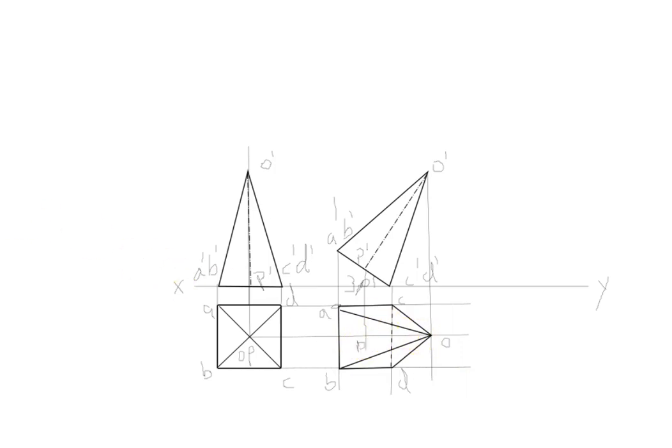Fine. So in fact we can also draw the axis. For example, let us do that. Let's draw a line from this to this and make that a hidden or dashed line. Now in fact that has to be not a dashed line, it has to be a center line. I'm sorry, it has to be a center line. The hidden lines should be dashed lines.